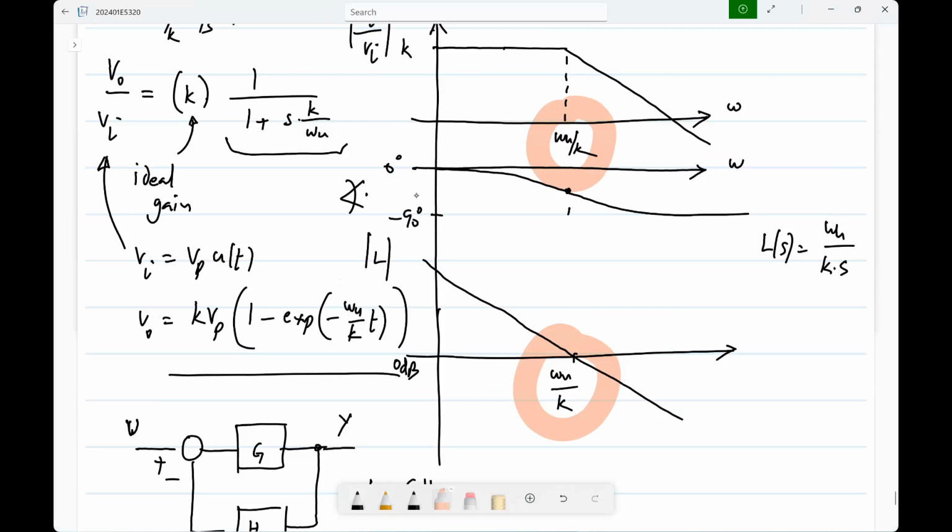That is, below the unity loop gain frequency, you have a lot of loop gain. When we come to op amps, you will see that you analyze your circuit with ideal op amps, you will get some result. And then when the loop gain is very large, it will behave approximately like that. When the loop gain drops off below 1, there is no feedback. It's like having open loops.